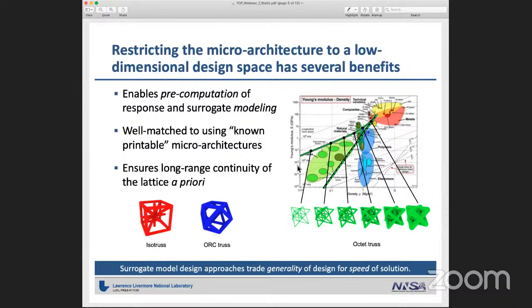So the scaling is not a uniform exponent. It depends on the density, and it's not as steep as we typically assume in SIMP. This is a slope, or an exponent, of 3 for the SIMP value, and the real response asymptotes to a value of 1 at low volume fraction.